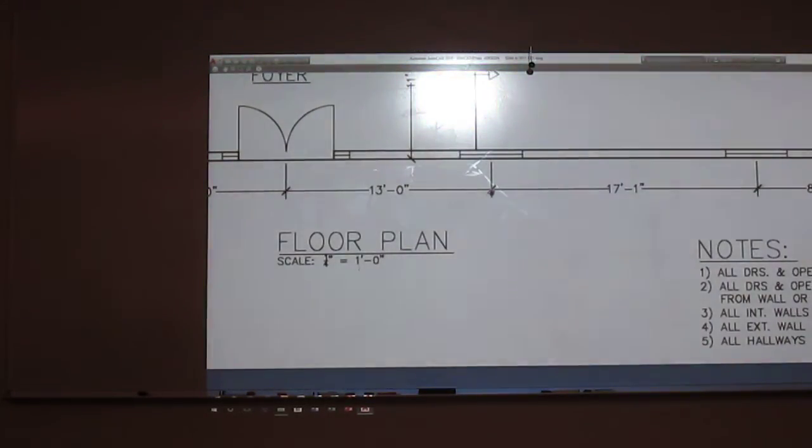When you look at these slash marks, they need to print at an 1/8 inch. This dimension line needs to be a 1/2 inch off. This little gap right up in here needs to be a 1/16. This has to go an 1/8 past. That's what I'm talking about, is all these standards.